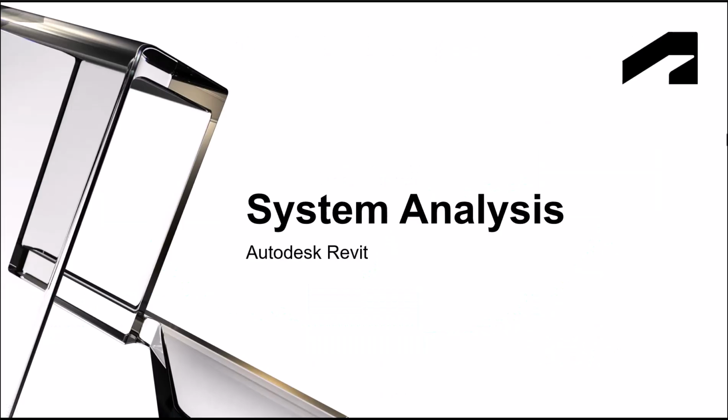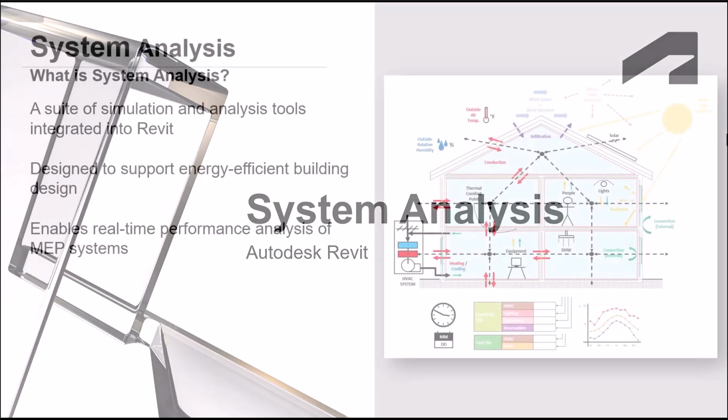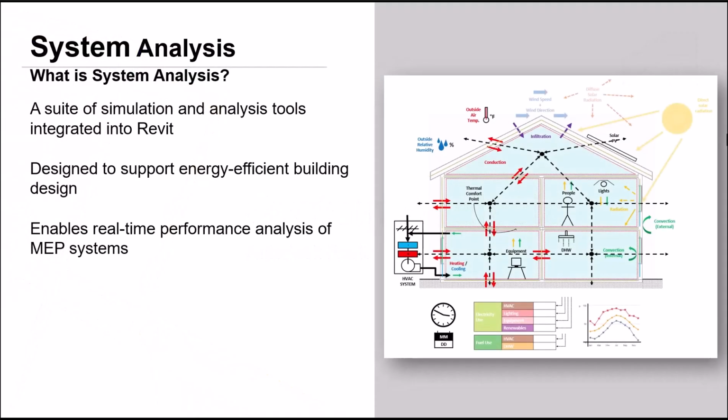Okay, so let me continue by introducing system analysis. System analysis is a suite of simulation and analysis tools fully integrated into Revit. Imagine this: you're working on an HVAC design, and before you even start drawing a single duct or pipe, you want to understand what the building really needs. So how much heating or cooling is required, where does the air need to go, is the envelope efficient enough? System analysis helps us answer these questions.